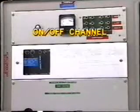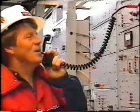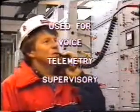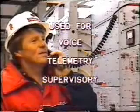The on-off channel is off for most of the time and is only triggered on under abnormal conditions, allowing the same frequency to be used for both transmitting and receiving blocking signals. This also allows the channel to be used for other forms of communication, such as voice, telemetry, or supervisory information, all in addition to its role in protection. Of course, the protection scheme always takes precedence and will interrupt other transmissions when required for protective relaying.